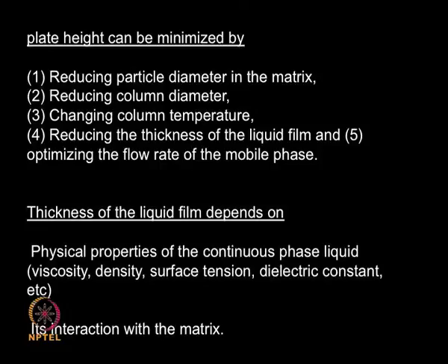Now any particle present in your stationary phase is going to be covered by a liquid film. This liquid film is going to be dependent upon the physical properties of this continuous phase liquid, like viscosity, density, surface tension, dielectric constant, so many factors actually. So this liquid film is going to offer some resistance to the solute that is going to attach itself to the stationary phase. So smaller the liquid film, faster will be the attachment, that means the resistance will be less. Bigger the liquid film, resistance will be more.